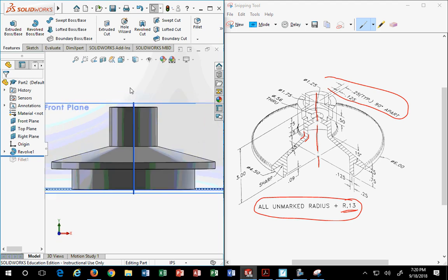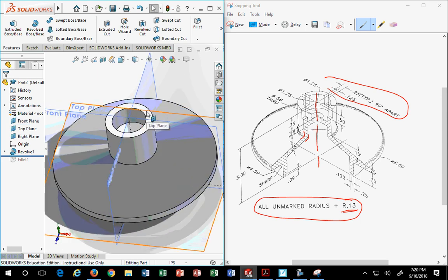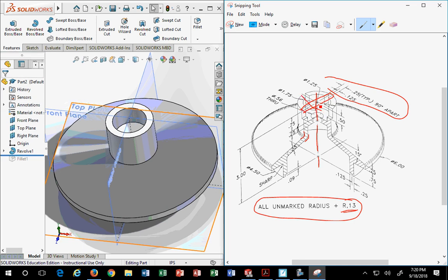I'm going to go to my front view, for example, and you have a cut right in there. There are 2 ways to make these slots. See this? This is a cut in this direction. If I'm going to use a mill, like an end mill, like a cutting tool, I would just slice across and do this in one shot if I had the right tool, or I'd nibble away at it to get that right shape.